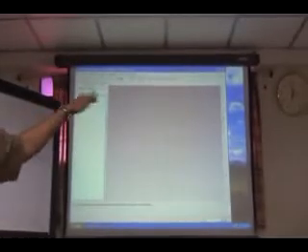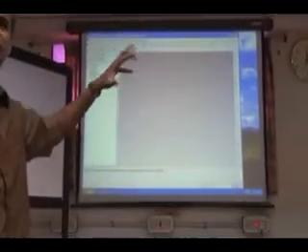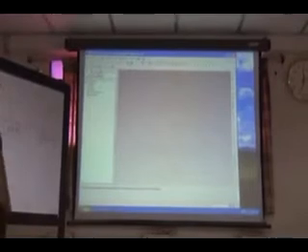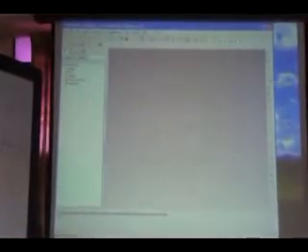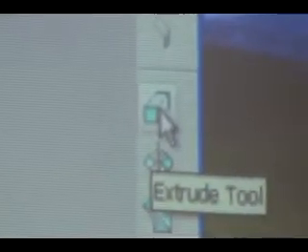In a design package, you see here, I have three planes perpendicular to each other. It's a three-dimensional environment, and I can create a 3D model itself. You see here, I'm creating an extrude. Using the extrude tool, I can draw a section. Suppose I want a hexagonal or square prism, I can draw a square. If I want a shaft, I can draw a circle. That I can extrude to a height, to whatever length you want for that model. So this is an extrude.